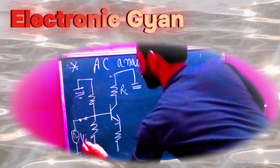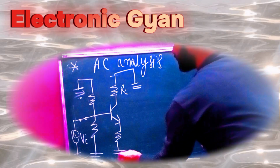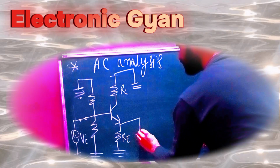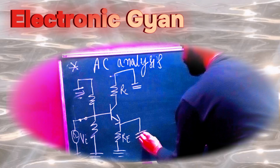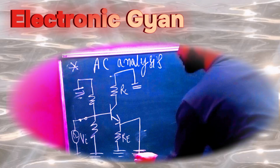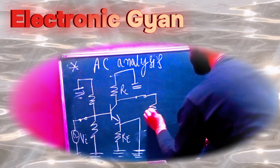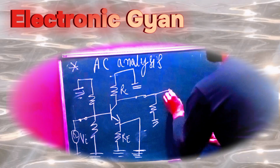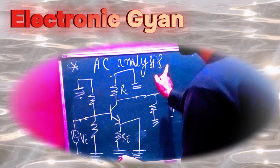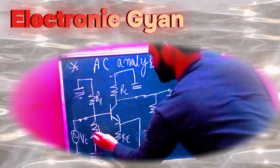The small signal gets coupled through this coupling capacitance. The emitter resistance gets bypassed by the bypass capacitance, which will also get short circuited. The output capacitance also gets short circuited, and here the load comes into the picture, with V0 positive and negative. This is my AC analysis, the small signal analysis of the common emitter amplifier. These are my bias resistances.